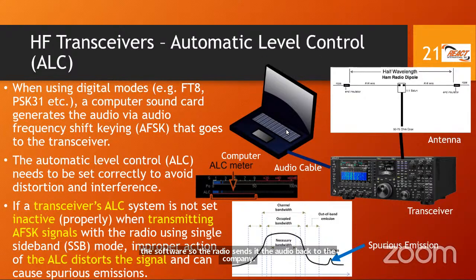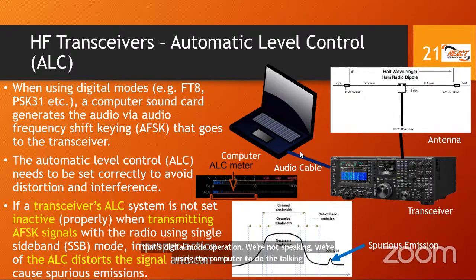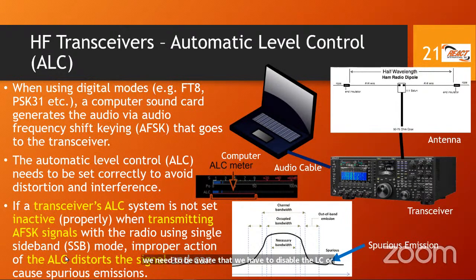So digital modes. Of course, one of the challenges with these modes, and we need to know that we're using AFSK. What is AFSK? Audio frequency shift keying. So we're using audio. While we're not speaking, the computer is generating audio. So we can say that that mode is via AFSK, audio frequency shift keying. And when we're doing that mode, we need to be aware that we have to disable the transceiver's ALC, because if we don't, the signal could be distorted. And this is an exam question.